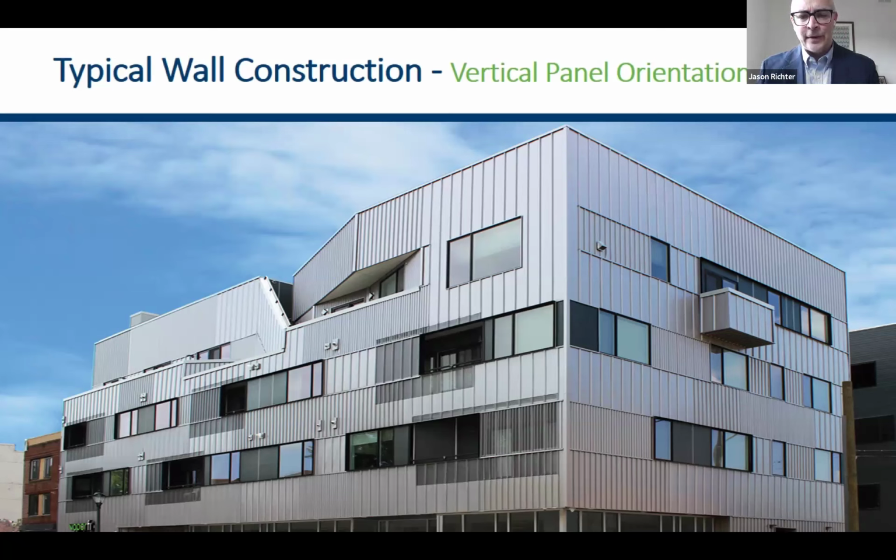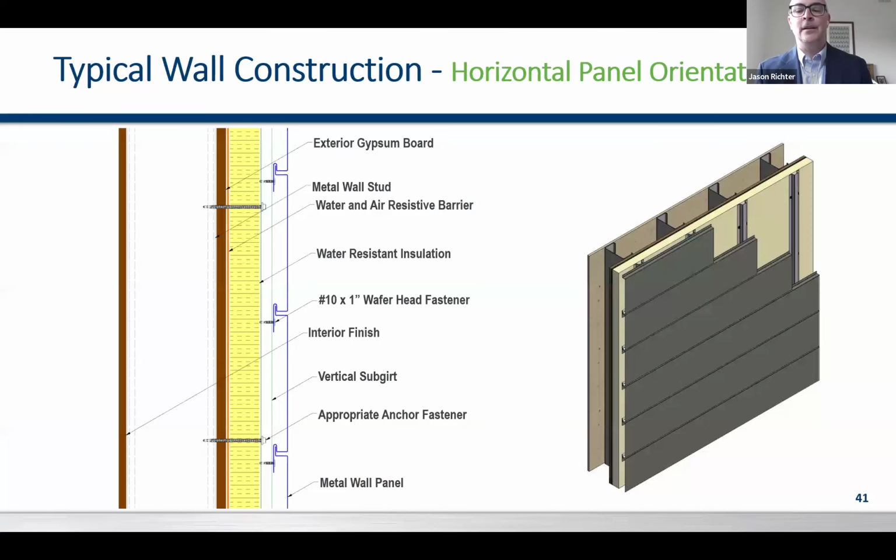One other thing that you'll note here is there's a lot of horizontal breaks. This is in part to do with the wood framing topic that we talked about earlier, where wood will dry out and contract, and especially once the building's fully loaded, it'll start to shrink a little bit more, whereas your panels will continue to be exposed to the elements and expand and contract. So making sure that you have break lines at your floor to floors, or something similar like with this at the window lines, breaking it up even more frequently, really helps to contribute to the overall design of your rainscreen, being a really solid part of the design.